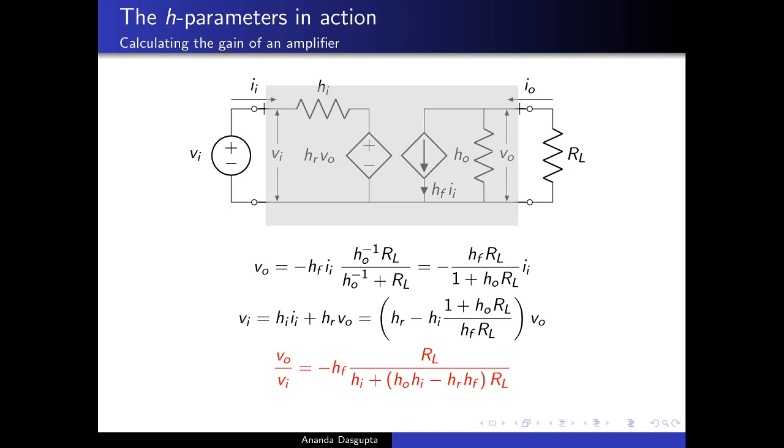These are all calculations we could do, and for example, we could also talk about the fact that the output voltage decreases when the load resistance decreases so as to allow more current to flow. Essentially it is a sign that there's an output admittance. The output is not just a controlled voltage source.